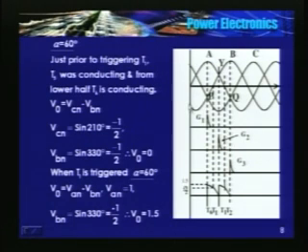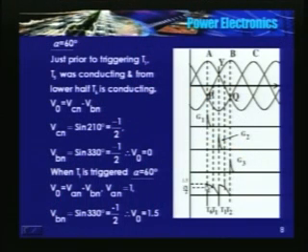Whereas VBN is still at 330 plus, so it is again minus half. So VO is 1.5 times the peak value, or 1.5 per unit. See the difference now. For alpha from 0 to 30, we had the peak value of root 3. As alpha increases above 30 degrees, the peak value comes down. Now with alpha equal to 60 degrees, we found that the peak value is 1.5, and the minimum is touching 0.